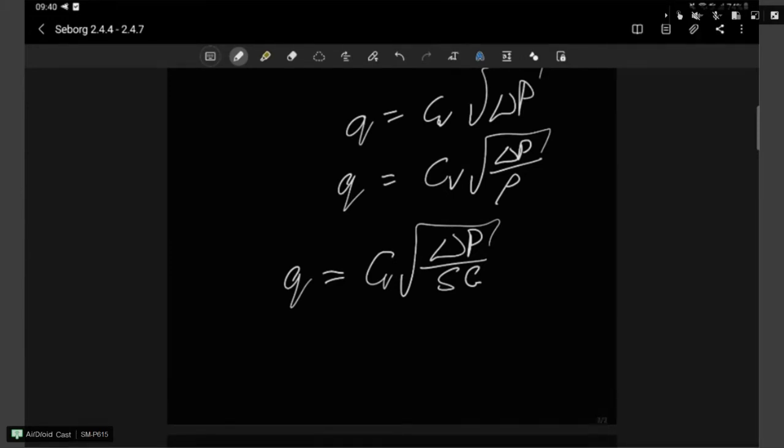For a valve, it will be this value. It's something that is actually experimentally determined. They do it for a range of flow rates. If you use it for something totally weird, like a non-Newtonian flow or something like that, then it will change. It's not going to be the same. And in any case, this equation, if I'm not mistaken, doesn't hold for non-Newtonian, but regardless of that. So does this clarify this issue a bit?